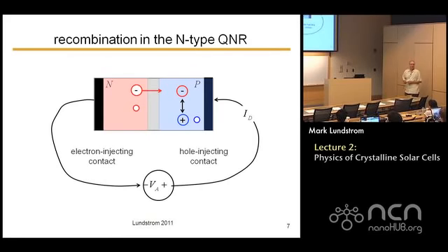There are more electrons than there are supposed to be in equilibrium. The system always reacts by trying to restore equilibrium, which means it'll tend to recombine. If it recombines with a hole, it means now I have a missing hole on the p side, and the p side is no longer electrically neutral. So an electron comes out of the valence band of the p side and out in the metal wire, and that creates a new hole.